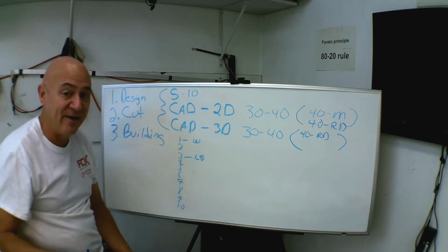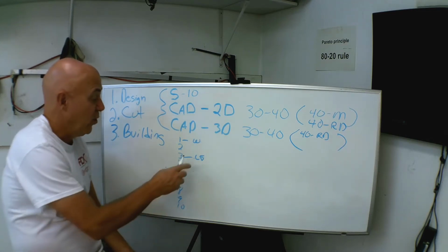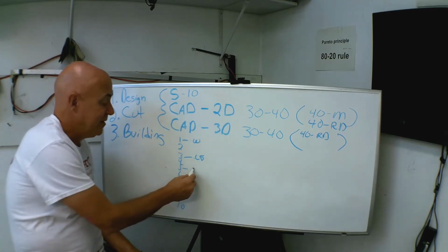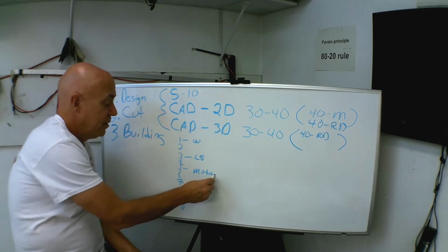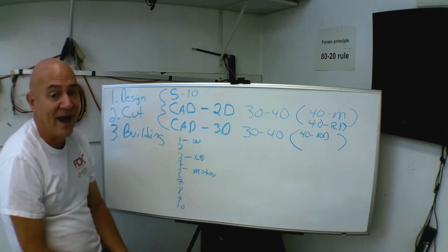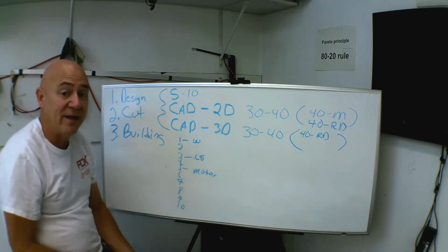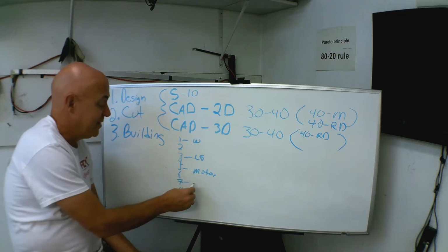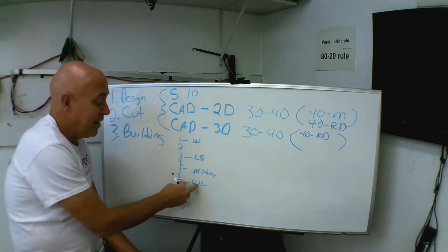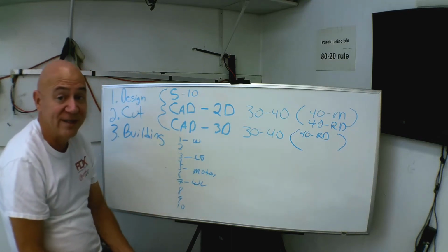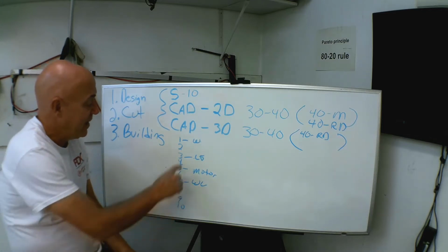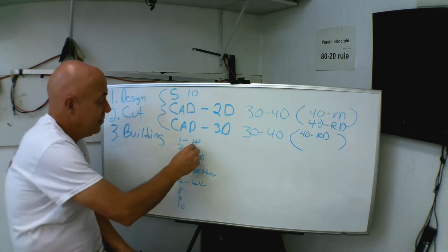Is that right? Yeah. 23 more pounds I'm putting in that airplane. On landing gear, I didn't design for that 23 extra pounds. So landing gear is going to be a big issue. Now, let's say number 5 is the motor. Is that weight going to affect the motor? Am I going to have enough power? Well, I've already known I've got gobs of power. I do need to go back in and verify. Let's say number 7 is the wing loading of the airplane. I do know with my higher weight, I need to go back in and verify my wing loading hasn't gone all to ape shit.